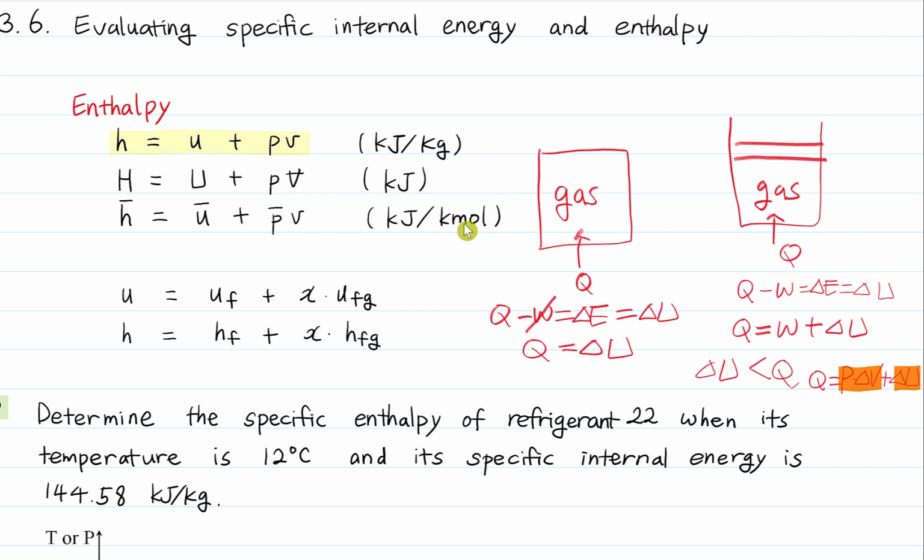If the substance is a two-phase liquid-vapor mixture, the quality is used to show the ratio of the mass of vapor to the total mass of the mixture. So the average properties of the saturated vapor and saturated liquid mixture can be expressed using the quality. Specific volumes, internal energy, enthalpy, and entropy may be expressed using a quality.